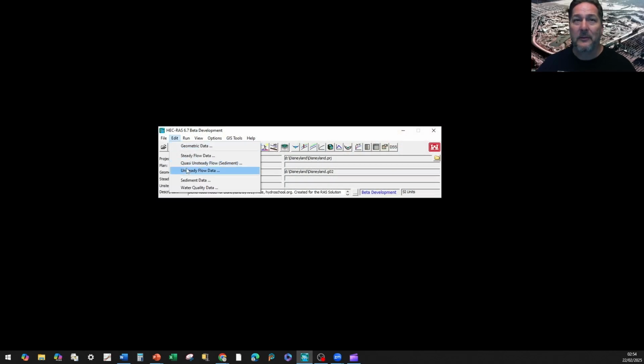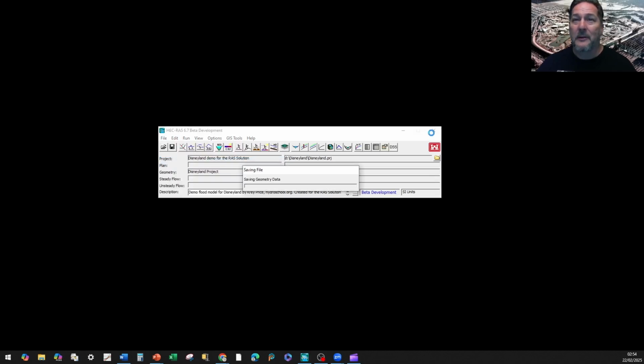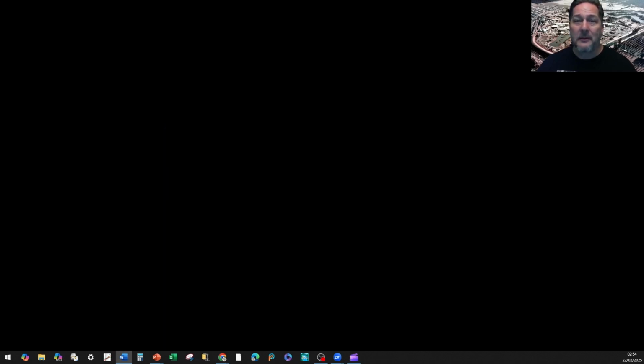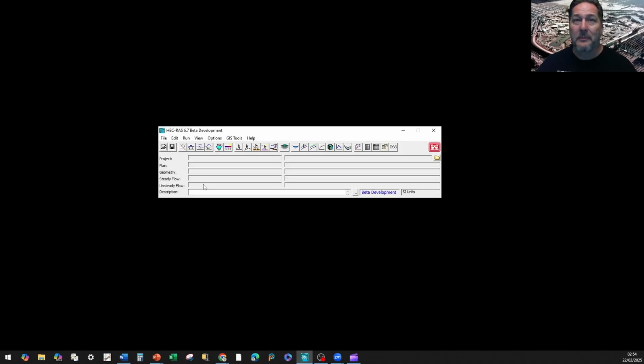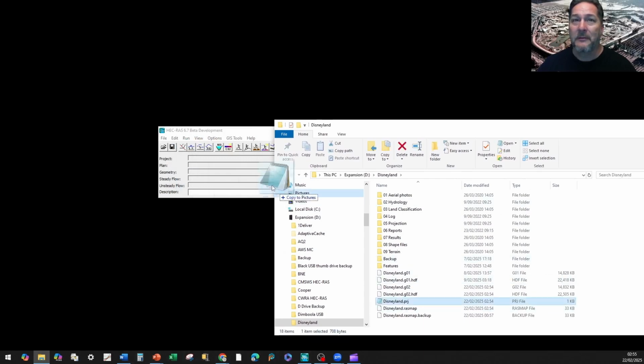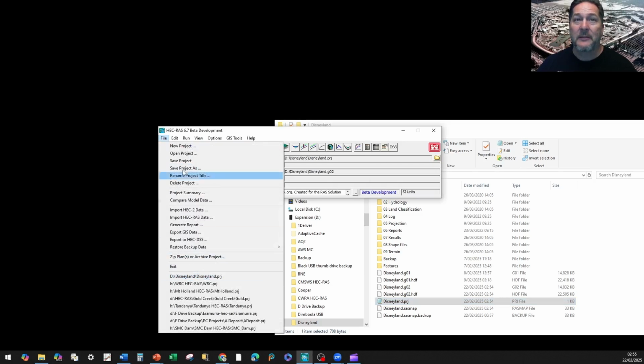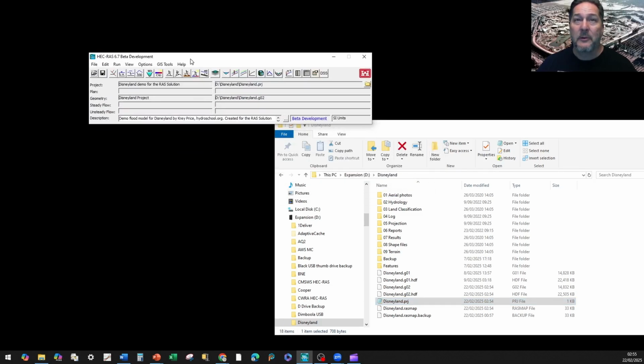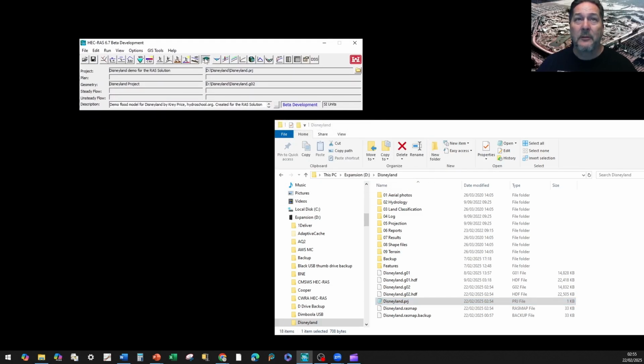And sometimes I like to just save the project, go out of HEC-RAS altogether, and then when you come back in, sometimes that wakes it back up again. And when you're first opening up a project again, one thing I hadn't mentioned before is you can always just take this PRJ file and just drag it in here. The other way to get to it is under File. It'll be the last thing that you worked on here. You can just pull that drop down. So let's go back into RAS Mapper now, and we'll see if it has woken itself up.